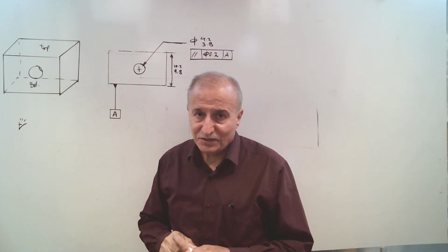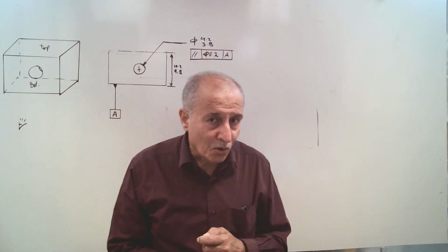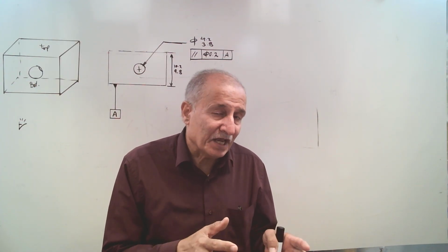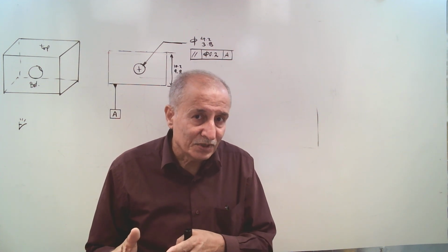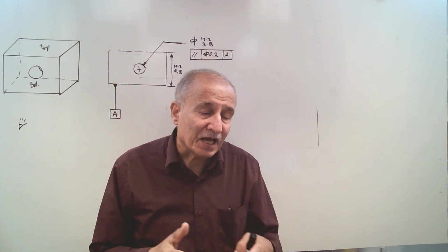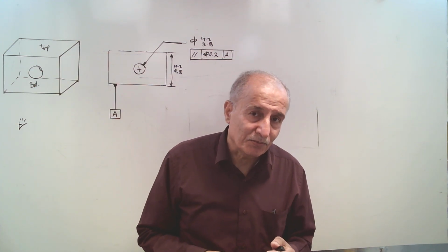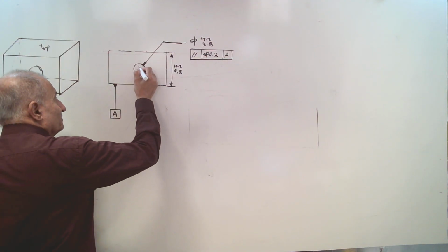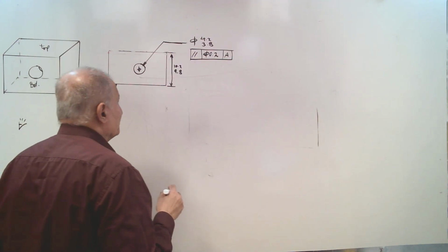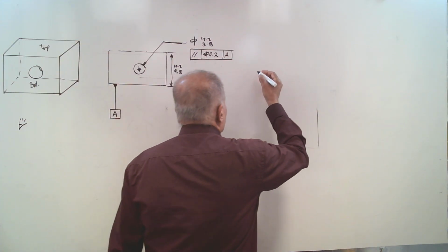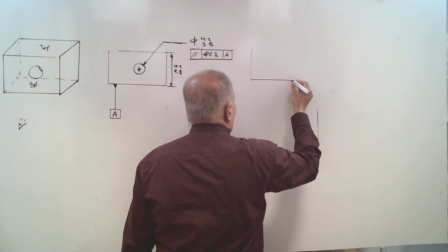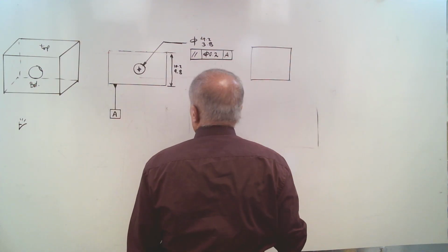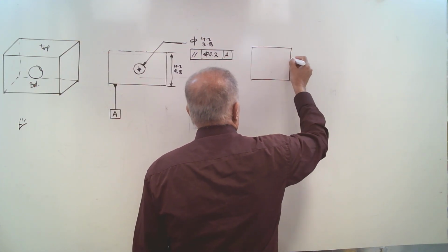It means that the axis of this cylindrical hole must be contained in a tolerance zone that is parallel to datum A. What is the zone shape here? Zone shape here is a narrow cylindrical object, size 0.2. Let's show another view here, the side view. If I show the side view of this object here, I have these holes as well.